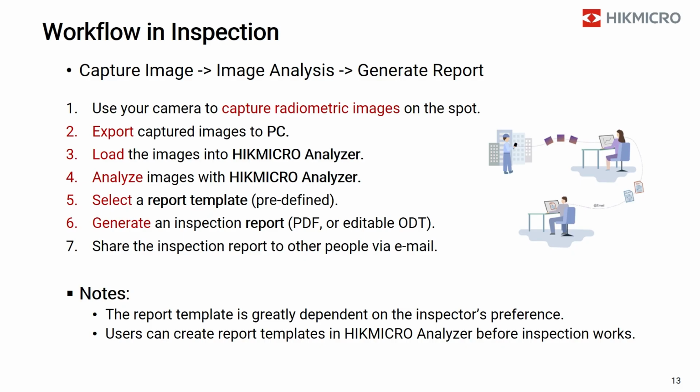Thirdly, load the images to HIKMICRO Analyzer. Fourthly, analyze the images with HIKMICRO Analyzer. Then, select a report template, which should be predefined. Next, generate an inspection report with the file format of PDF or editable ODT. Finally, share the exported inspection report to other people via email.